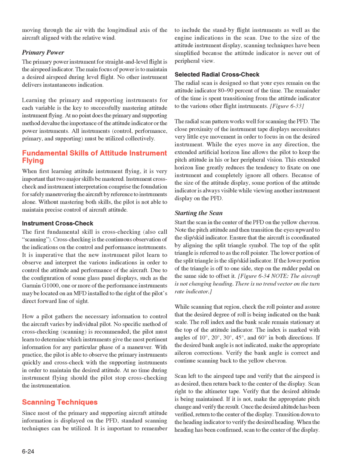Instrument crosscheck: the first fundamental skill is crosschecking, also called scanning. Crosschecking is the continuous observation of the indications on the control and performance instruments. It is imperative that the new instrument pilot learn to observe and interpret the various indications in order to control the attitude and performance of the aircraft.